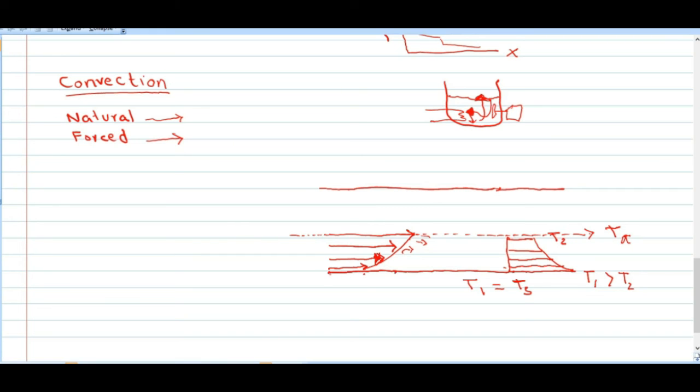However, at the surface where the velocity is very small, approaching zero, heat transfer called energy diffusion occurs. Therefore, heat transfer through energy diffusion occurs only in the layer which is at very low velocity, and this heat diffusion is only because of the collision of the molecules.